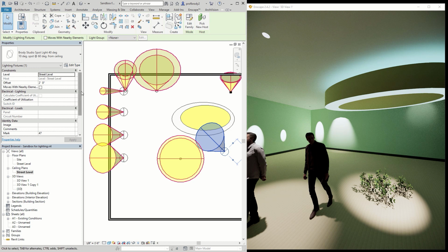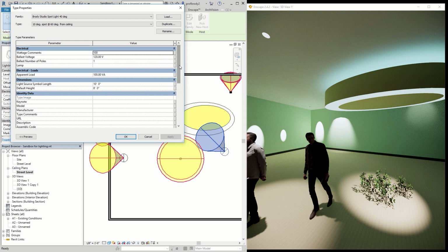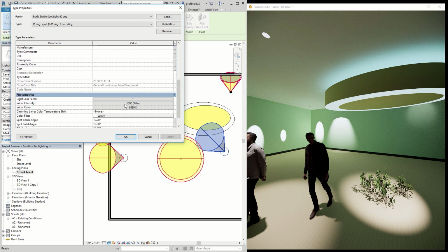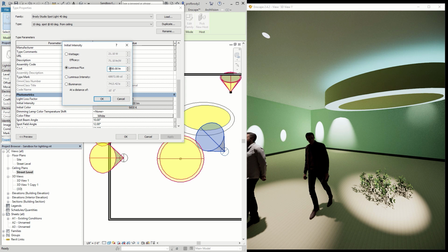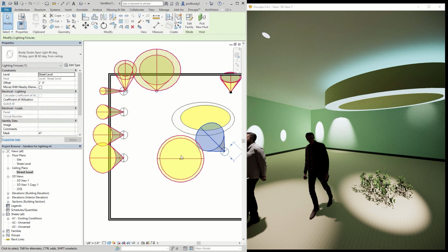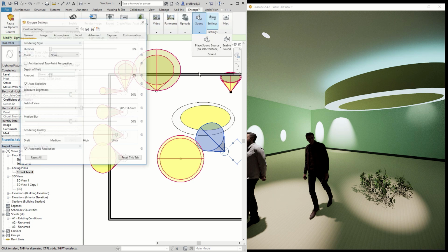And you can come in, I believe it's set to kind of the power of the sun here. They're supposed to be pretty bright. Let's see, 1500 lumens is pretty bright. I can change this down to 500 and apply. And you should see the light level drop down significantly. So you can kind of tweak things, and of course you can have more than one light fixture on an object. Enscape will absolutely adjust the overall light level based on everything you have going on in your project. So that's when you'll want to go back to your settings and start fiddling around.